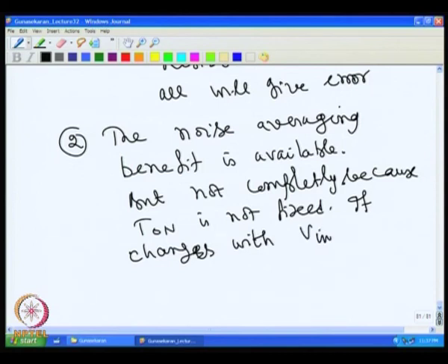Nevertheless, this is a poor man's A to D converter, which is used in the microcontroller world extensively. The equations are there. For example, almost all the microcontroller manufacturers provide this kind of conversion solution. For this purpose only, most of the microcontrollers have an inbuilt comparator. You can also put the comparator outside, and then switch the timer on and off and realize the A to D function even if you do not have a comparator in the microcontroller.